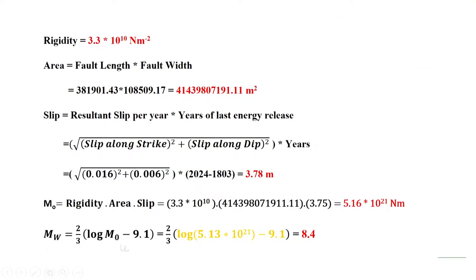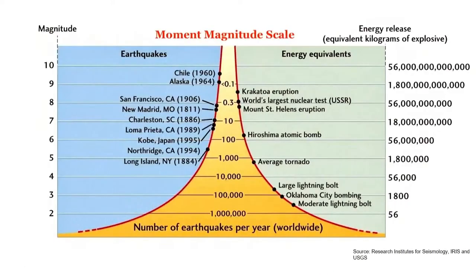The total energy that has been stored corresponds to magnitude 8.4, and of it, 6.3 and 6.7 energy has been released. If you subtract this energy, still huge energy is there along the plate boundary, which will be released in the upcoming years. This is how we have validated, and we have quantified the seismic hazard.